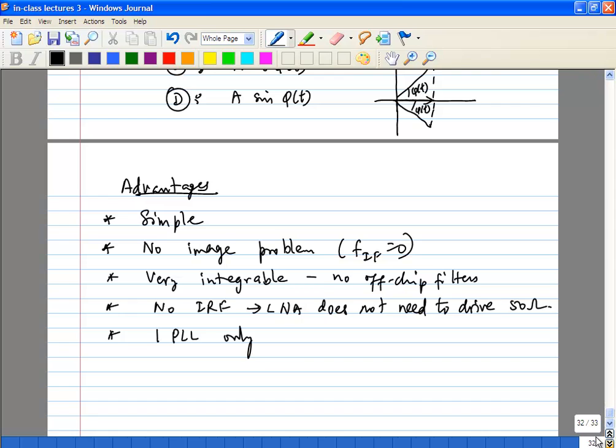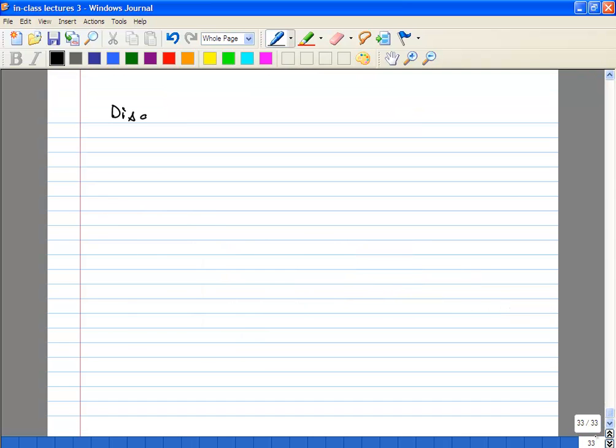Okay. So what are the disadvantages? Doing the channel selection in the baseband, we need to provide large dynamic range for the RX. Large dynamic range for what? For what in the RX? The entire RX part. Actually, what you will see, we'll come to that. It's a trade-off between the dynamic range of the ADC and the analog path, rather than the overall RX. Most of it, there is a trade-off involved. We'll come to it.